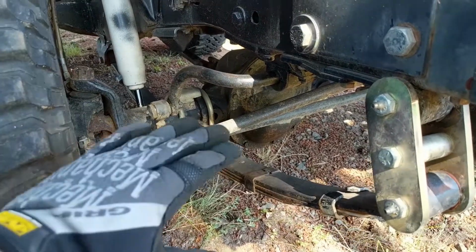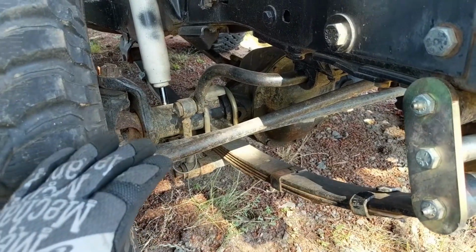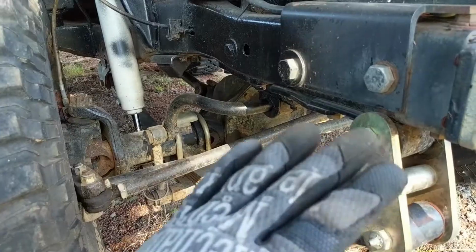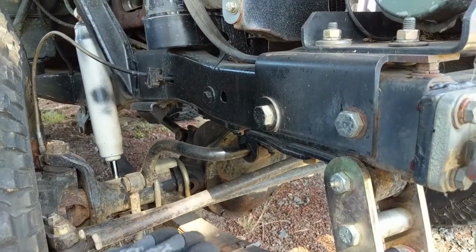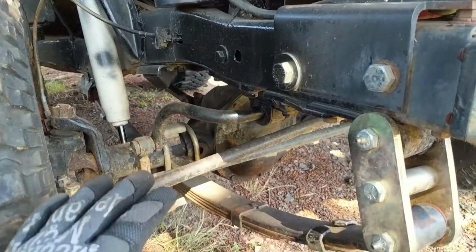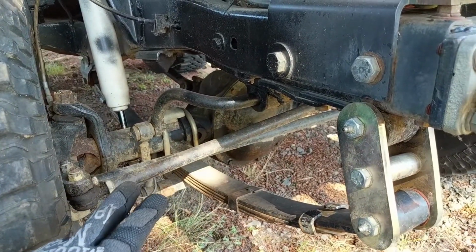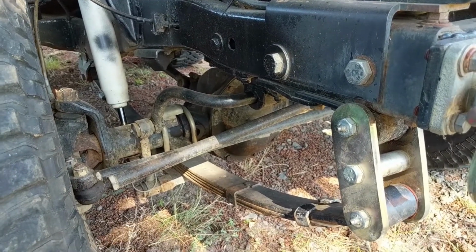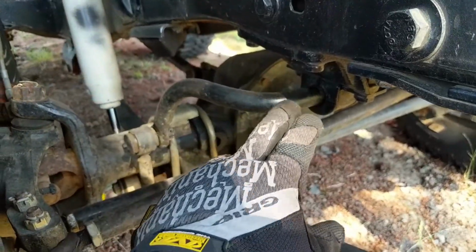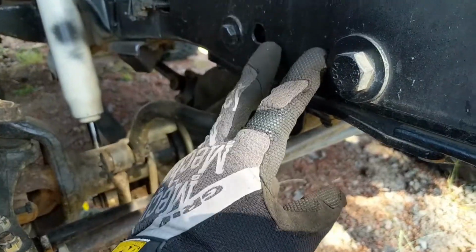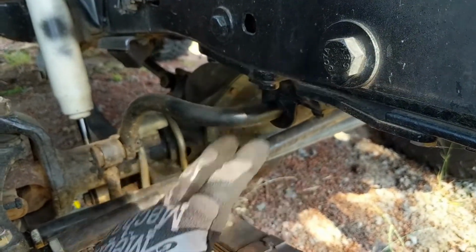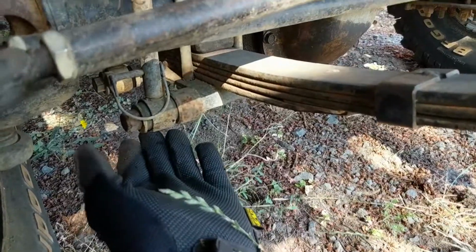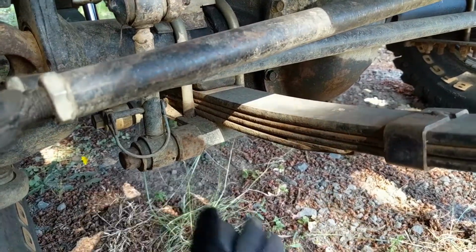So the tires and the axle move with every irregularity in the ground. That energy goes into the spring, and the spring provides cushioning for the rest of the chassis. So anything above the spring is considered sprung weight. Anything below the spring or connected to the bottom of the spring, in this case the middle of the leaf spring, is going to be unsprung weight. So we have the sway bar mounted to the sprung weight of the chassis, and it is being connected to an unsprung component right here on the sway bar end link. So this is how it's connected.